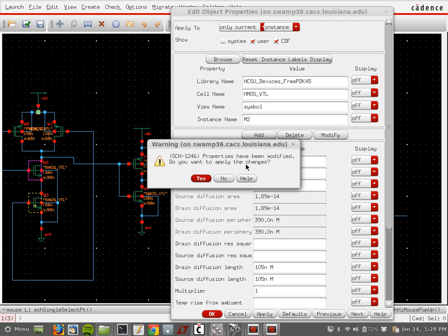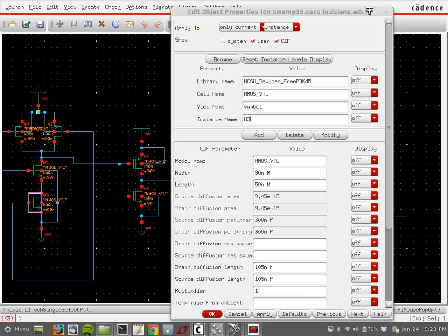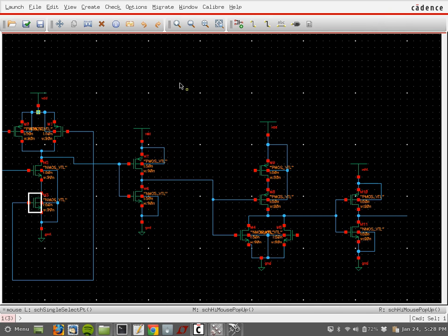So in the previous design, we used a smaller NMOS, but the size of PMOS is twice as large as NMOS. Right. Yes. Okay. You're right about this. So before sizing any of the gates, let's deal with the inverters.